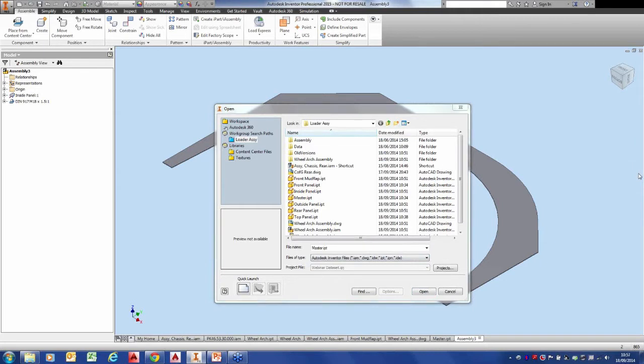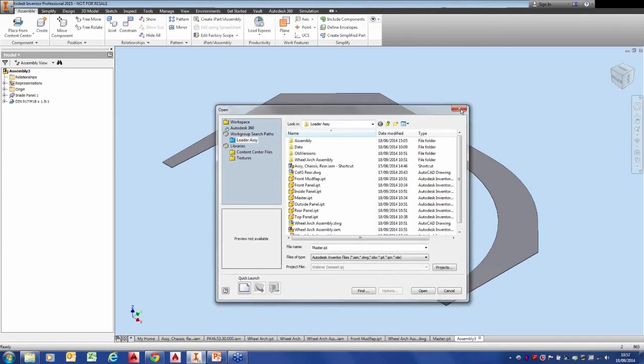So I've got a question about bridge design. Does it apply to Inventor? So there are things you can do in Inventor. You've got things like lots of tools for nuts, bolts, washers and fixings. So you can apply those in. You can also do things called frame generator, where you can draw the shape of something. So you can draw the profile you want a beam steel shape to follow, and then by clicking those beams you can join them together and you can trim those up.